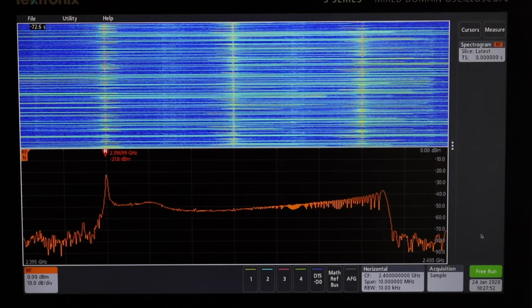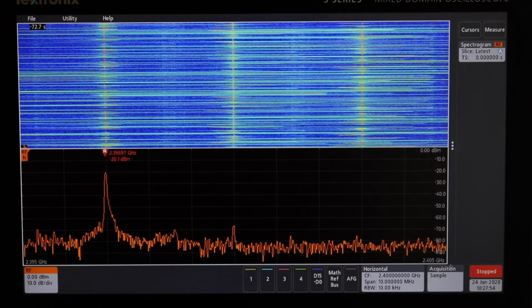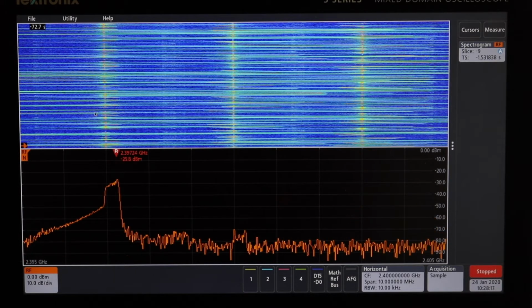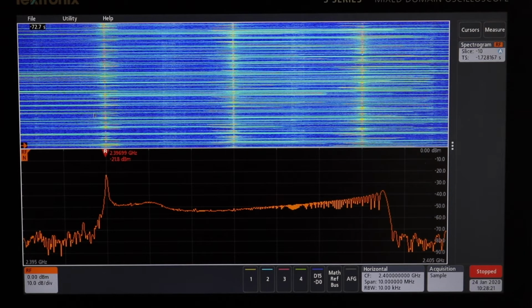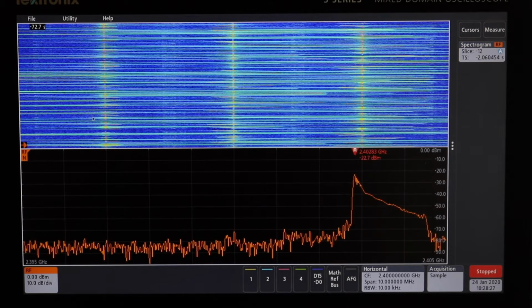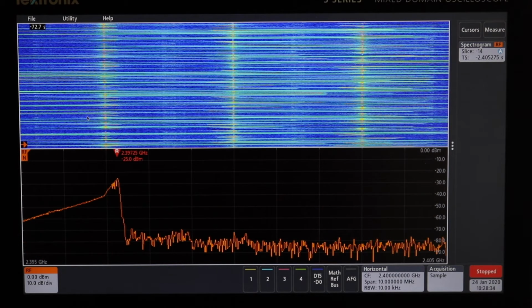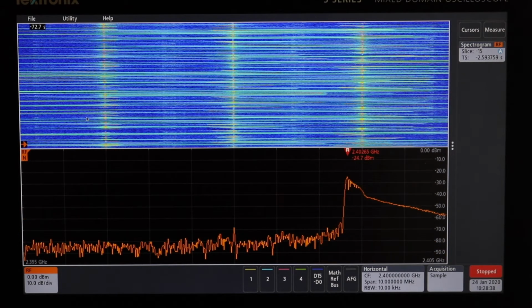Okay, that's that one run through. We'll stop him again, and with the same approach, you can now scroll through looking at the individual areas that you might have. Okay, so there's one of the pulses there at 2.4 gig. Got another one down at 2.39, 2.39 again, and back up to 2.4. And back across, so you can start to see the pattern generate across the frequency hop.